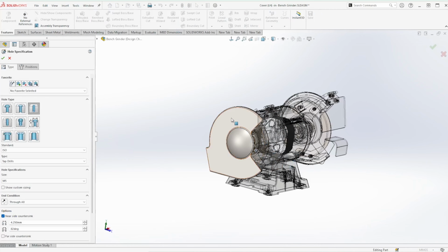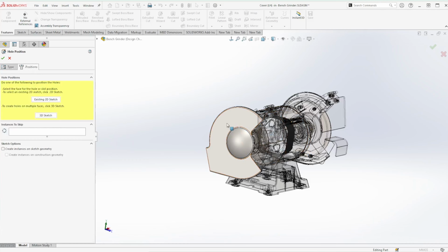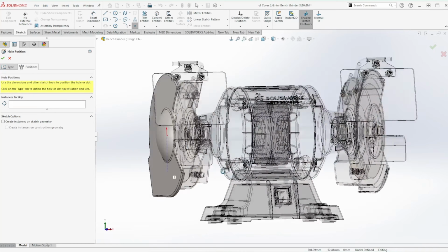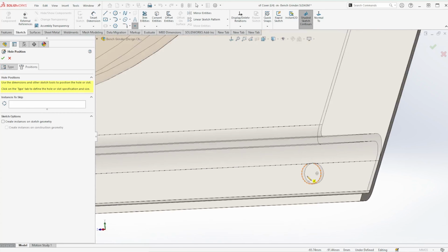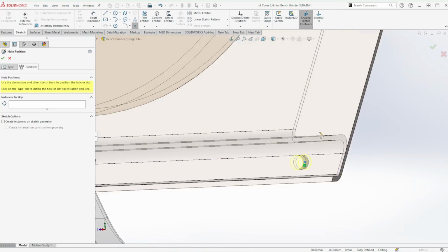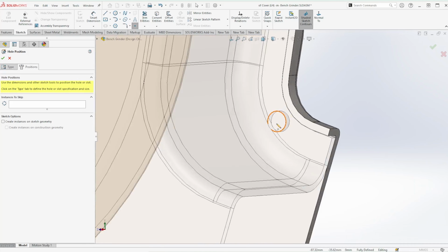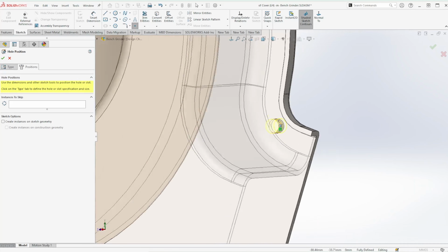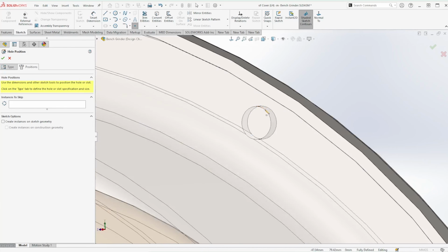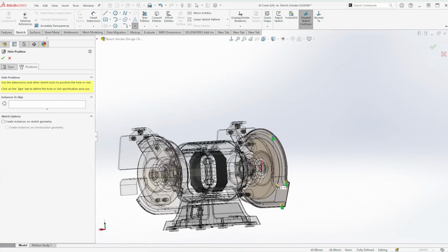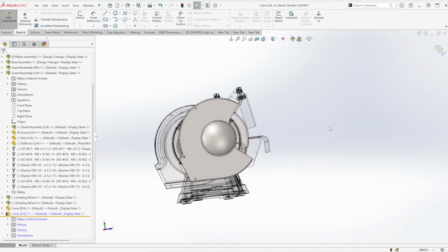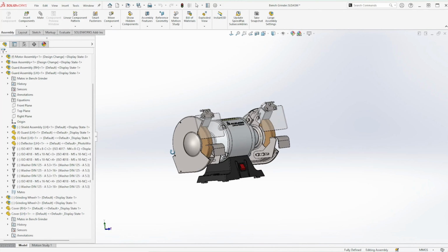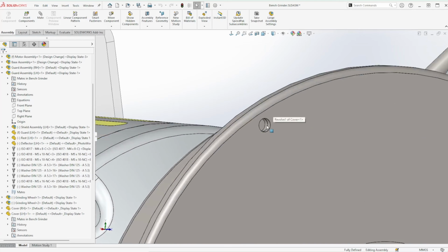So just using the hole wizard tool, I will place these sketch points for the hole positions onto these edges where it's going to connect. It's going to create an external reference to that guard component, right? So by using this edge as my guide, it's creating a permanent link to that other model to guide where those holes will be positioned, right? I'll exit the part. Now we're back to assembly mode. So you can see the holes line up perfectly.